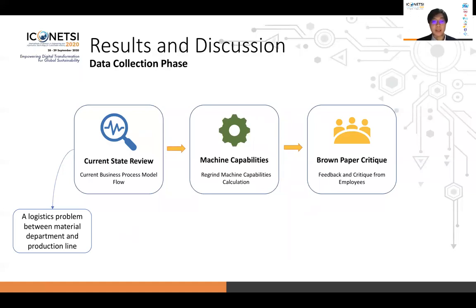As information, there are 2 types of material used in the production. The first is virgin material, a new mixture of plastic resin and colorant, and regrind material, which is recycled material from the waste of the injection molding machines that goes to the crusher or regrind machines before it goes back to production as material.